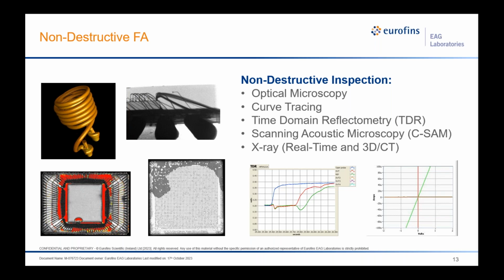The image just right of that is a 2D X-ray image of a profile view of a wire bonded device. You can probably see that there is a wire bond that's actually lifted. Based on how the molding is around that bond wire, it gives you an idea of when it happened. If that bond wire is fully encapsulated by the molding, this break most likely happened before encapsulation, which gives you an idea. It's not something that could have happened in the end application or in the field. It happened prior, in assembly.